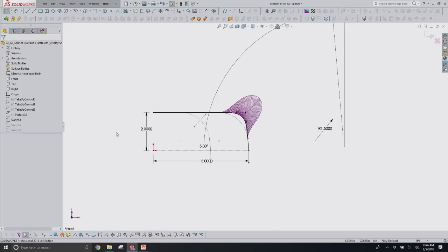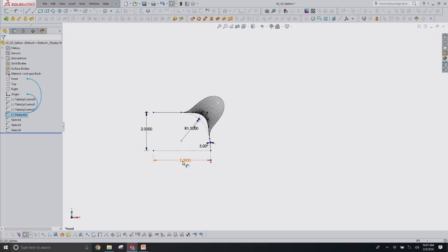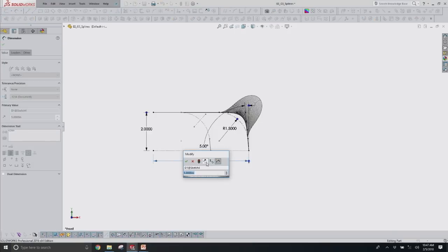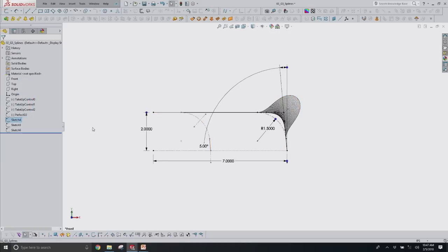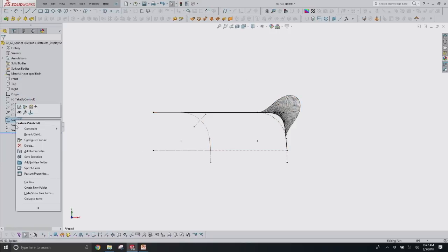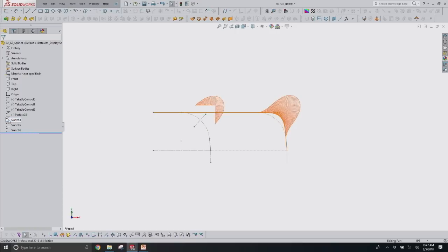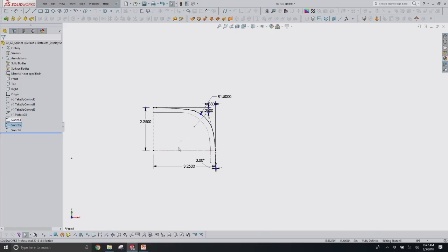One way I found was that, so I guess in the sketch it was working, but if, let's say, I double click and I'm not actually in the sketch here, and let's go 7. Let's see if I can do a little rebuild. Yep, perfect. So this example is working. This is great. It wasn't working earlier. So all I want to say is this is a perfect way of doing these nice parametric, really smooth transitions, but you have to treat them cautiously just because sometimes the control vertex points want to stay locked in space.